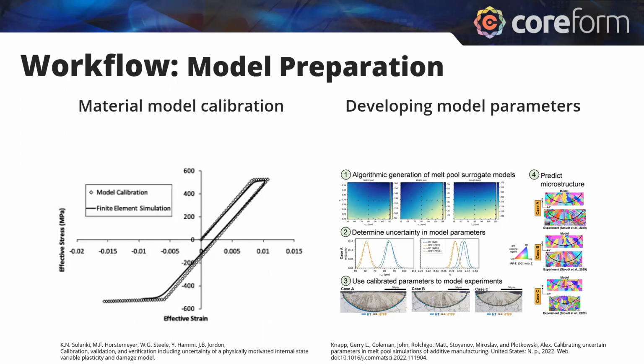There's also model parameter development that you'll likely be doing. For instance, on a melt pool for laser welding or additive manufacturing, you might be doing some small breakouts just to calibrate what laser parameters I need in order to get a weld pool that looks like what I'm seeing experimentally. Again, before I can calibrate a lower order model for my actual engineering problem.